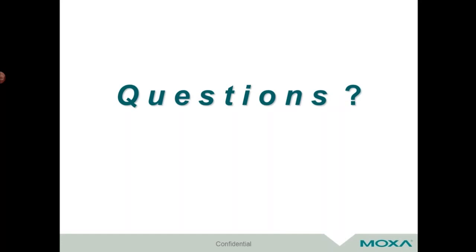Yeah, I think that is one for me here. Good question, and I kind of alluded to that but didn't explain it totally. The most common type is to utilize 2 individual fibers for transmit and receive, as shown on the diagram in the presentation. However, there is another technology called WDM, or wavelength division multiplexing, which is able to share a single fiber between the edge devices by shifting the frequency of the light.